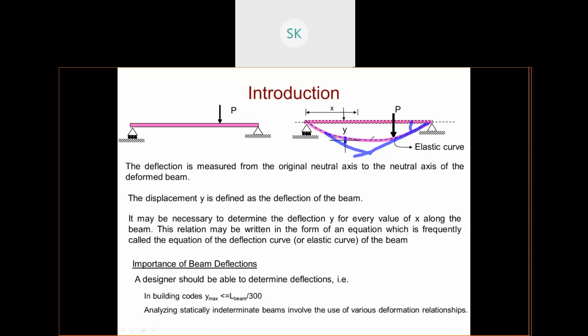When you come to the middle part, there will be no angle, right? So theta is 0 at the mid span. Where the deflection is maximum, your theta will be 0 because the tangent is not making an angle. Let me erase this part. If I draw a tangent to this elastic curve, sorry, this was not the angle, this was the angle. This is the slope. But when I draw a tangent to the middle part, there is no angle, right? And if you see the deflection at this part, the deflection will be less at this part, right?